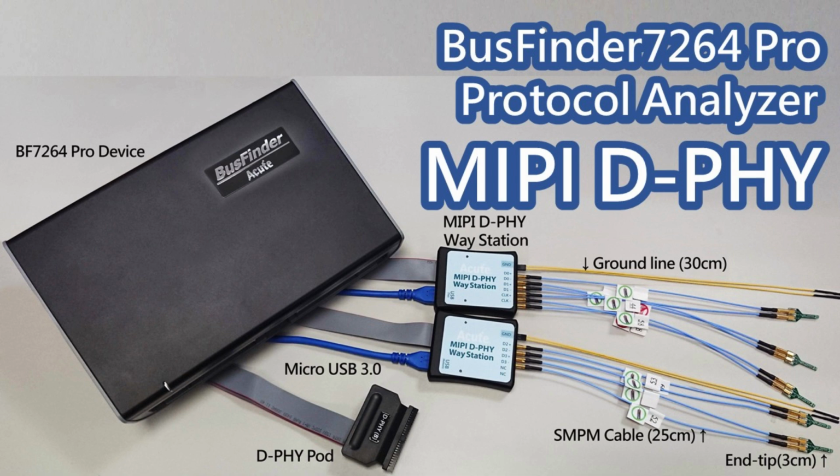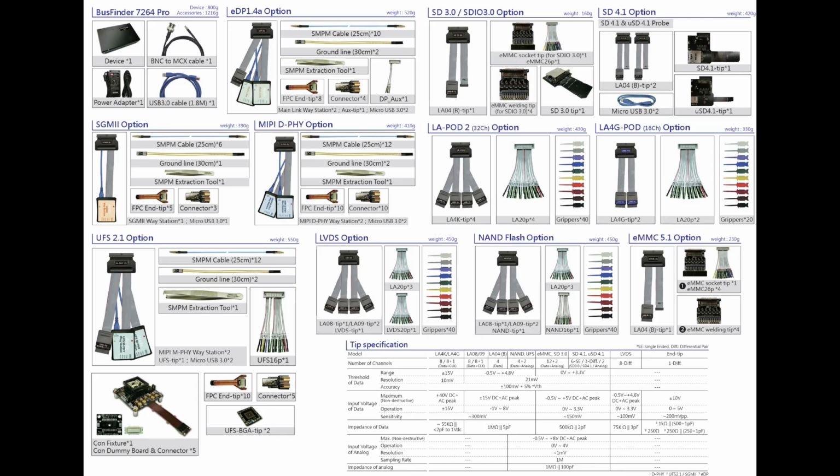The bus finder uses oversampling technology to capture data, so it remains stable across various signal speeds or even during dynamic speed changes. So far, we've successfully captured DSI signals at 1.94 GHz, and CSI signals at 2 GHz. Bus finder supports multiple options and helps you measure all kinds of high-speed signals.